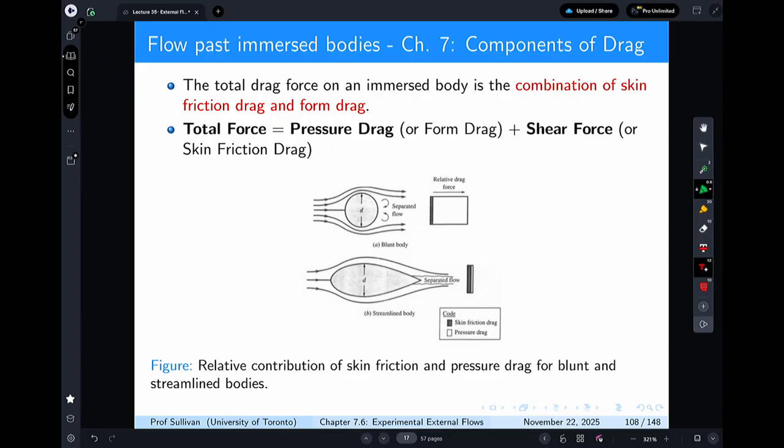Total drag is actually going to be a combination of both body forces, pressure drag, and friction drag. And so we deal with both of those by trying to streamline things. So you can see, for example, in the upper figure, that as there's a separated flow, you still have a separation that occurs. You can't get around it from geometry. You can try and deal with it by essentially extending that body by a little bit. So we do a lot of effort. All of the stuff I talked about in terms of the 1920s work done by NACA was devoted to the idea of trying to sort of quantify how these things behave.